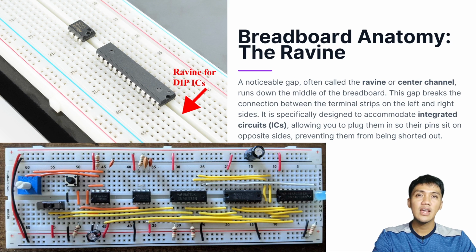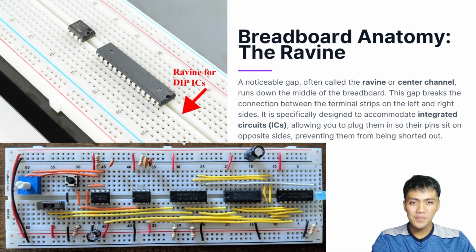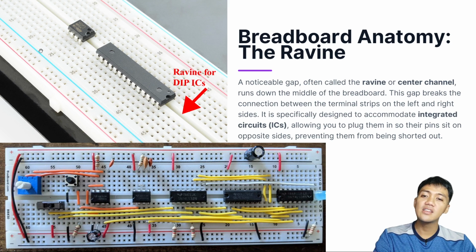In our breadboard, the space between the left and the right component rails is specifically designed to be enough to accommodate these ICs. Like this, the legs of our integrated circuits can easily insert into the evenly spaced holes in our breadboard, and on the other side, that can happen too.